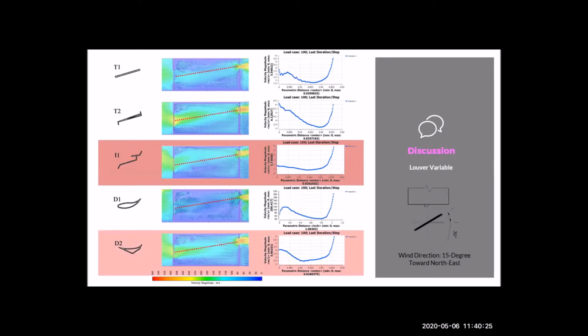However, velocity around inlets is higher than the preferable amount. Model T1 directs wind to the non-habitable section of the room. Thus, the T1 option would be the best choice for the classroom. Also, if the angle of D2 were to increase to 35°, results would show more similarity with T1.